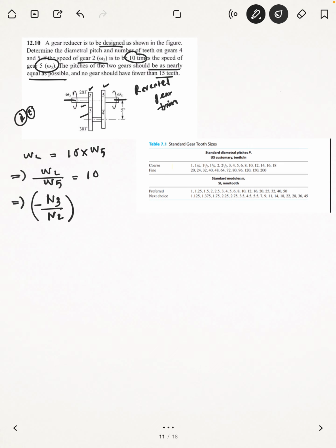Now we are on gear number 3, and 3 rotates 4 at the same speed, and then 4 is going to mesh with gear number 5. Here the same analogy applies: if one rotates clockwise, then the other is going to rotate anti-clockwise.